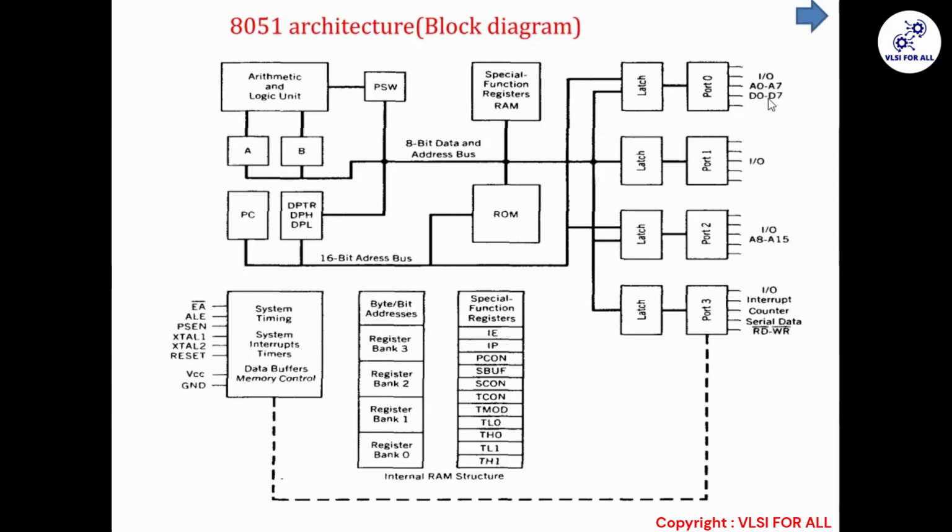So it will be fetched through these 8 pins and come inside. Or whatever data I'm generating here, I can save on the external memory with the help of these pins. That's why I need D0 to D7 also. Good question, it was a very good question.